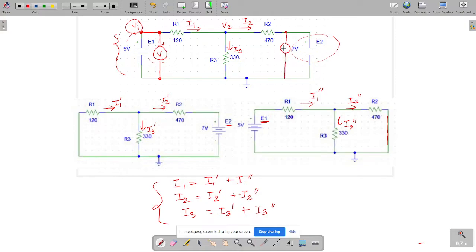So is this voltage going to measure V2? Oh, sorry, V3, ma'am. It's after R1, and ground. Yes, we can place it after R1, with the positive terminal connected after R1 and the negative terminal grounded. Okay, so this is going to give our value of voltage V2, and this is for V1.